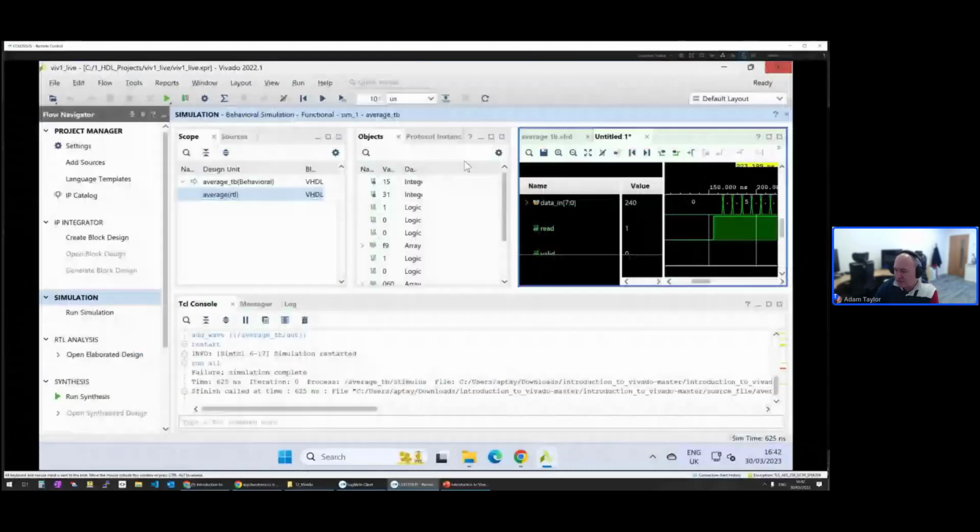So the question that's coming about debugging CDC crossings in simulations: it's actually very difficult to debug CDC in simulations because it requires you to do a timing simulation with all of the timing information put in there, which makes the simulation take a long time. But it also requires, because you don't know what the clocks are going to start up like, as the two clock domains are completely asynchronous to each other, that you find that sweet spot in simulation that causes the metastability effect to occur.